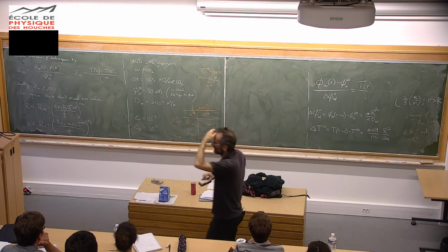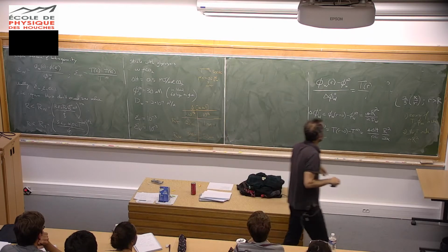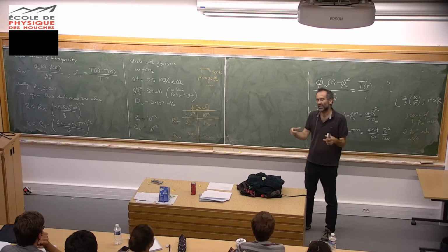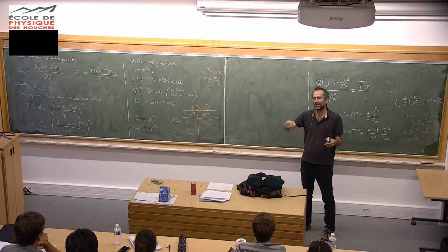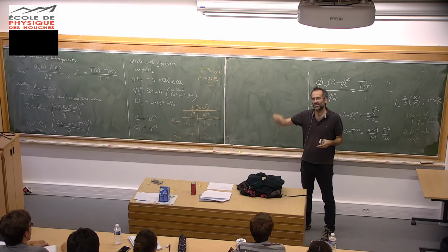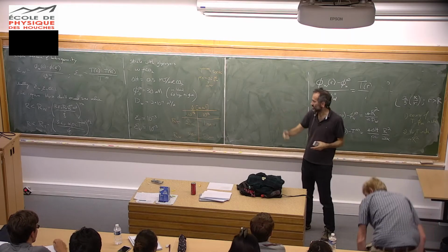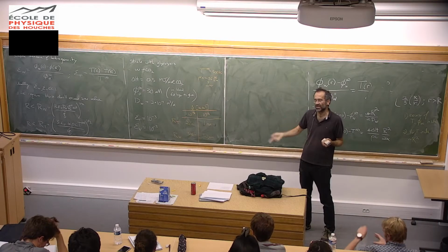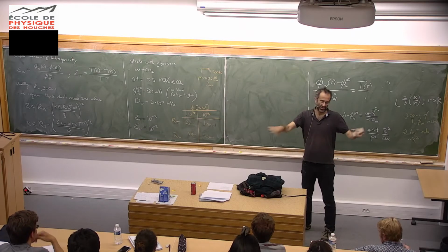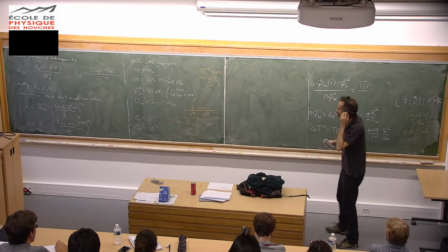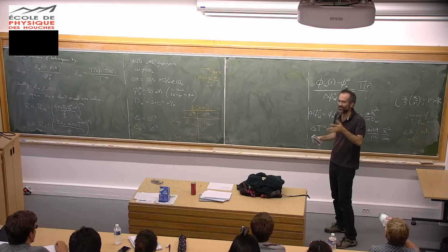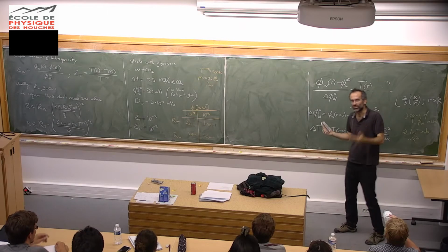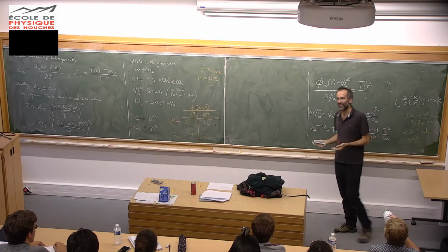Yeah, exactly. So at the end of the day, in that particular case, what's going to matter is the narrowest dimension of your sample. I think for all these calculations in different geometries, you wouldn't really have to redo the calculation. I would just use the same threshold, but apply it to the narrowest dimension of your sample. External convection will help, but will only change things by a factor of 2. It's not going to solve the internal problem. You can only solve the internal problem with internal convection.